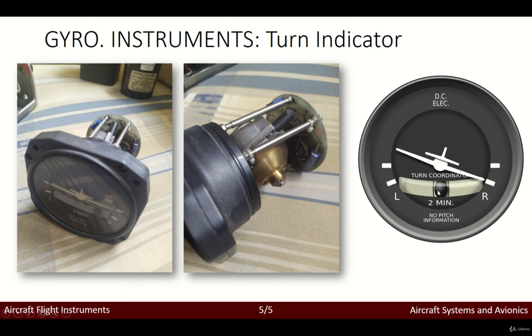So if we have it over here, this would be a 2-minute turn. I believe the maximum is more or less a 3 degree change of rate. So again, it's just an orientative way of understanding how the aircraft is moving, and also the nomenclature or the way in which we visualize this may change from aircraft to aircraft.